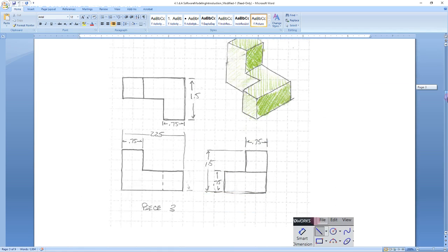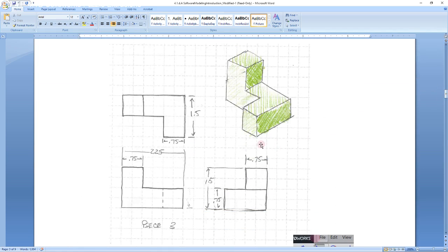What we're going to be modeling today is a puzzle cube piece. And what we're going to work on is an extrusion instead of into a sketch plane or away from a sketch plane that is part of the model plane. We're going to go ahead and sketch on a surface and extrude this little end. So with that in mind, realize that each one of these is made up of a 0.75 inch cube that's glued to another cube. So this width is 2.25 inches, 0.75, 0.75 tall, 1.5 tall. So we'll need those dimensions.